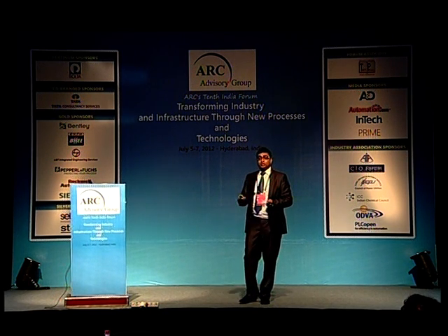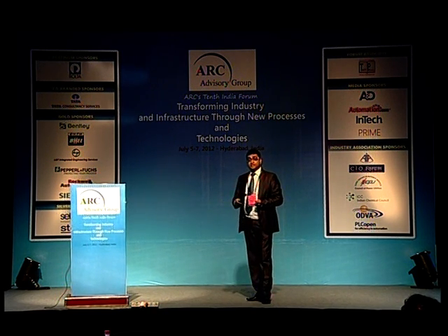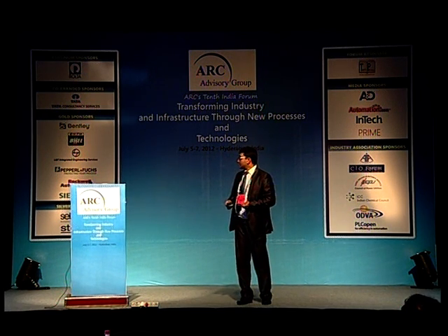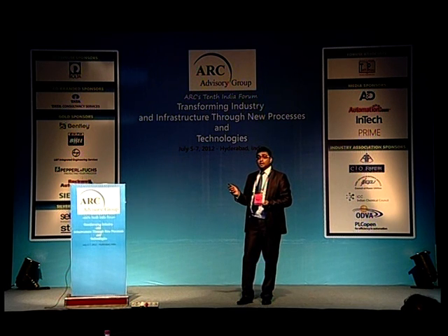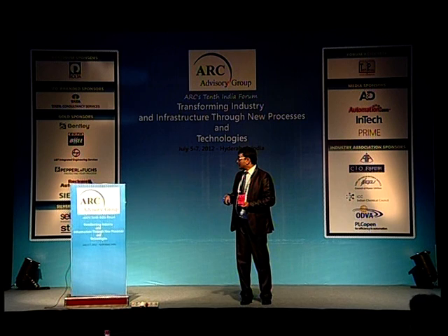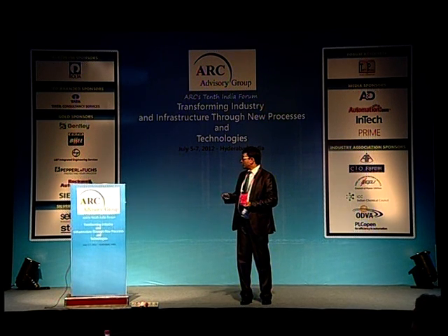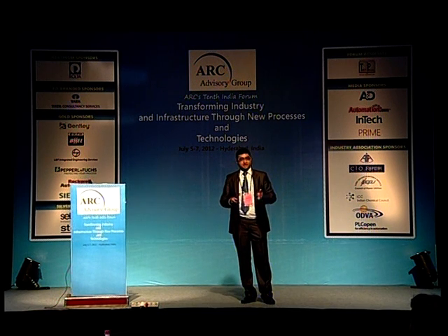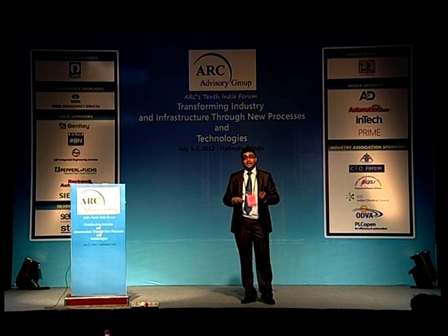The other important module which is helpful in today's power plant scenario, because you know that a lot of tube leakages are happening in power plants, is the metal temperature module. This module computes the different tube metal temperatures from the model, and first of all it gives you a calculated value all the time, because we have seen in the power plant that metal temperature measurements do not last very long.